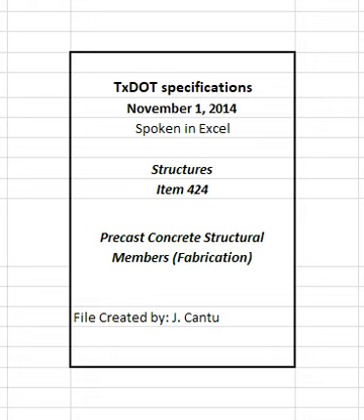Cool the aggregate by sprinkling or fogging, fine mist, with water, shading, or using an approved liquid nitrogen system and procedure. Cool the fresh concrete by using chilled mixing water, partially replacing mixing water with shaved or crushed ice, or using an approved system and procedure to discharge liquid nitrogen into concrete during batching. Apply a fog spray, fine mist, of water to the steel just before placing concrete when the temperature of steel forms, strand, or reinforcing steel is greater than 120 degrees Fahrenheit. Water droplets left on the form surfaces must not adversely affect surface finishes.